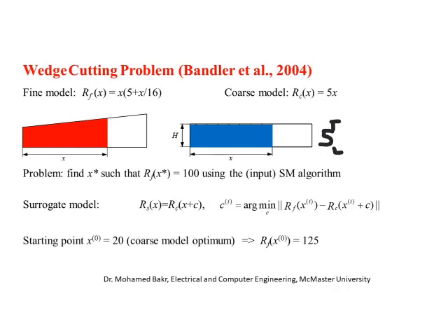Here I'm going to be using a single parameter extraction. If I want to determine that shift c in the parameters, I give it the area of the fine model at the given x, and then ask myself what c I should add to the given parameters such that the coarse model gives me exactly the same area.